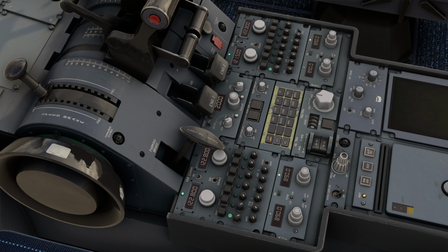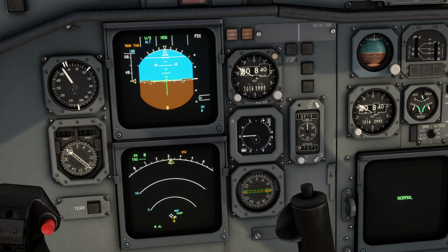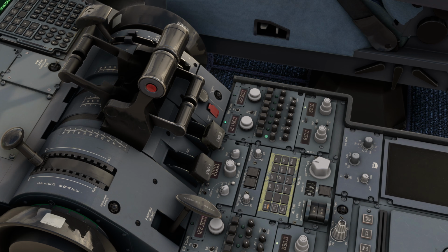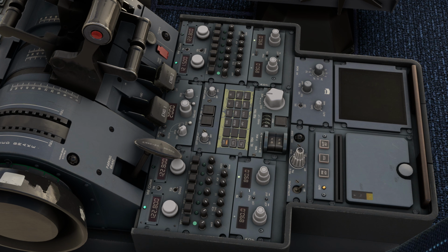Okay then, so moving further down, we select our transponder as needed. That's here in the middle, and we're going to switch our TCAS to above, and we can keep the range over here. So that's showing 6 nautical miles right now, and we're going to keep that, so we're not going to touch that. And that is basically it on the transponder and TCAS. Next up, we set our radios as needed, so we don't need an ADF today, so we can disregard that. We make sure that our rudder trim is showing 0, and do note, in order to reset this, you would need hydraulic pressure.